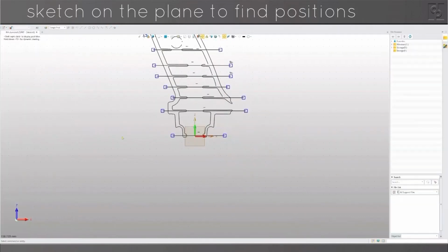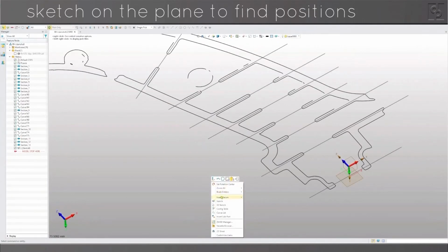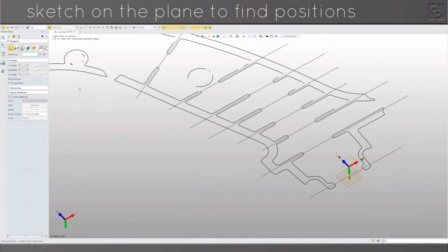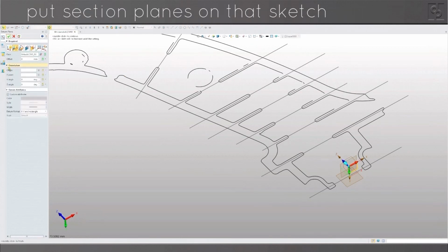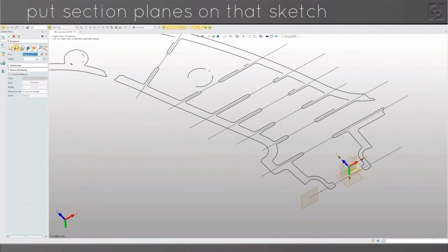The next step is to use the CAD coordinate system XY plane as a reference, and then create a plane offset from that through a point where the point is the end of one of the sketched lines. So that's selecting the XY plane and then picking a point for the plane that I've just created and repeating.